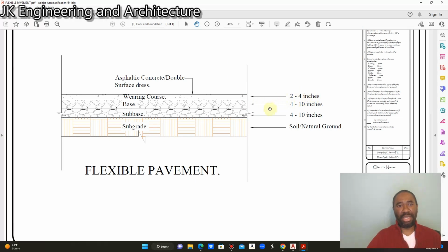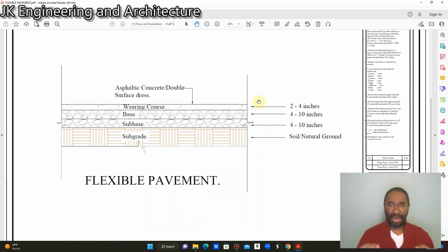So that pretty much is, in a nutshell, what the flexible pavement consists of. Before I move on to explain to you what rigid pavement is all about, there's something important I want to add to the flexible pavement, and that's the thickness of your layer structure is dependent on the structure number. So what the engineer does, the engineer calculates the structure number, goes to a chart, and he can get the thickness of the different layers dependent on the structure number.